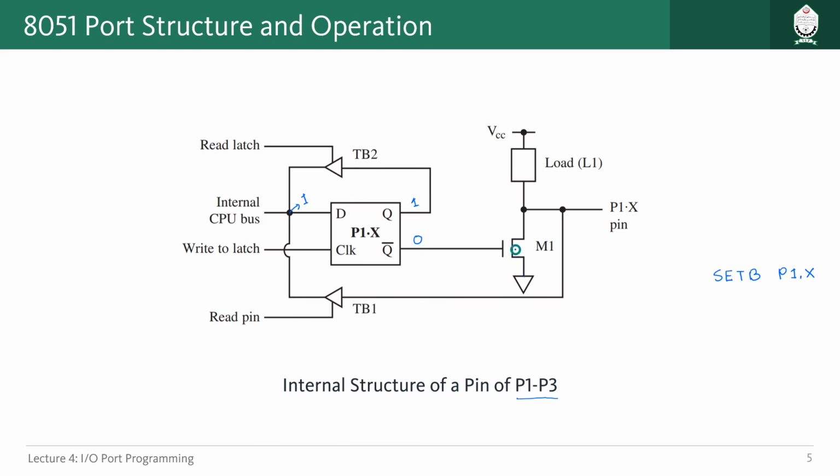So that will not enable our MOSFET, and this path will not be complete. This is an open circuit right now because we don't have enough gate signal to turn this path on. Because of that, at the output pin, we are going to get the VCC signal, or 5 volt. This signal will go to the pin because the voltage drop in this path we consider very low, so essentially we are getting the 5 volt here.